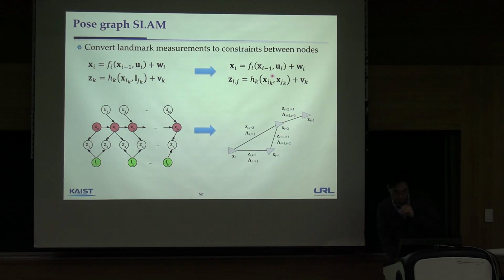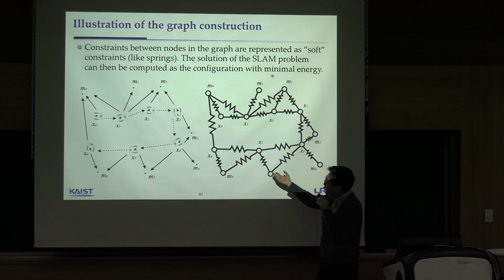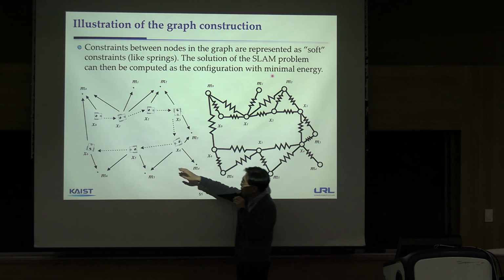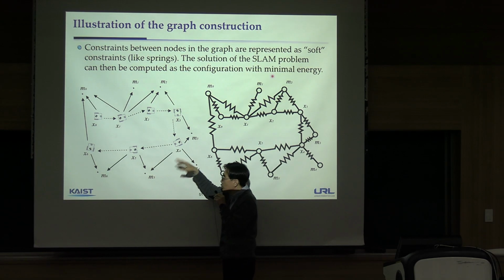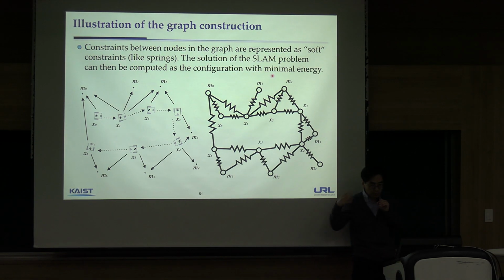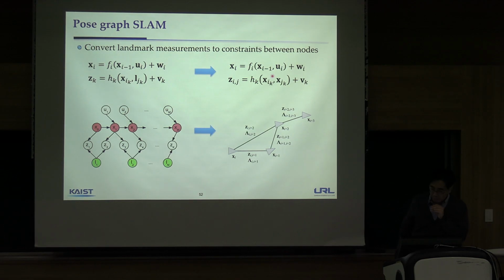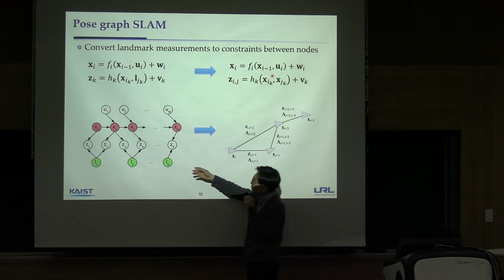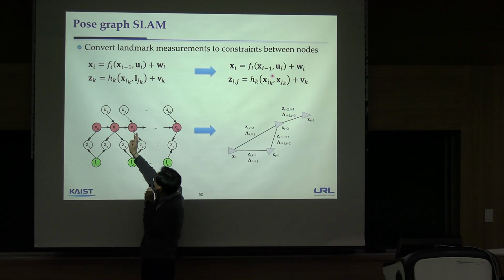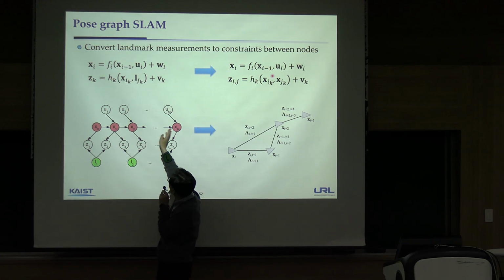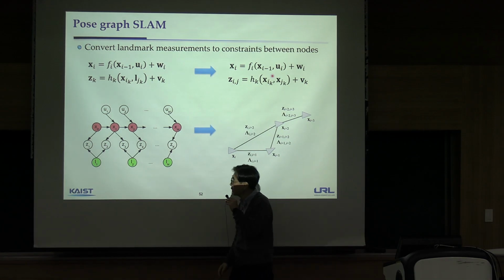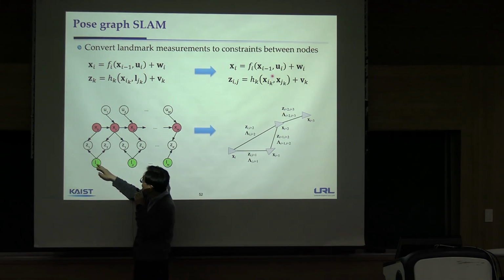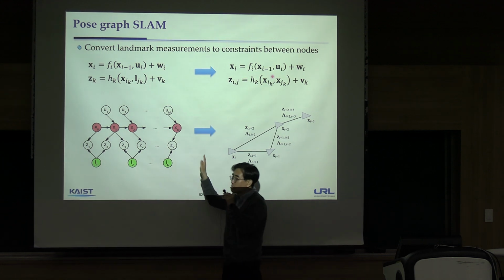So in this example, we utilized all the information. Nodes and also landmark positions should be connected all together. So this is quite complex. The original formulation was like here. The robot was in x0, x1, x2 up to xm, and at that time we have the control inputs u1 to um, and also we had measurements from z1 to zk, and using those measurements we have the landmarks. Quite complex.